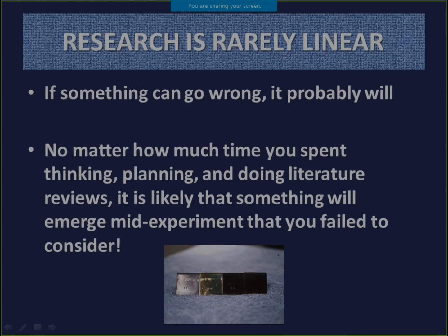But it turned out that one of our primary coatings that we were testing, and we were testing it because it was recommended and used in the preservation of silver, turned out to be completely permeable to hydrogen sulfide, at least at the thickness that we had applied it. And that's a common off-gassing product. So within the first week of testing, all of the coupons with that turned completely black, and it would then swamp out the results of any further analyses we wanted to do. And so we realized we had to stop and rethink the entire experiment.